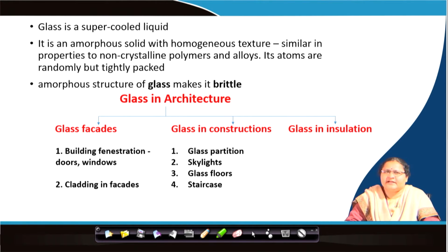So, these are the areas where glass can be used, but I told you at the very beginning that glass is brittle. So obviously, there should be different kinds of glass, or maybe differently treated glass, that will help in developing qualities like taking loads, not breaking, or not being dangerous or unsafe when it breaks. So, we have to know how those are achieved and where to propose which kind of glass, because all those special qualities add to the price.